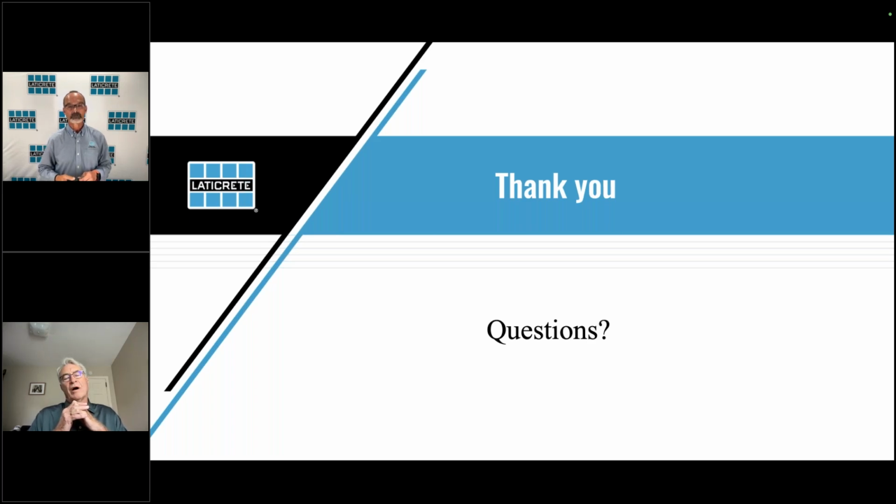So like every webinar, I talk about how important manufacturers' recommendations are. They supersede TCNA or anything that we have. And if this question came up and someone called, would you have a technical rep or someone that could go look at the compact gravel and help make a decision? No, not really. I wouldn't expect that. Yeah. Okay. We just don't know the history of it, right? I mean, gravel is one of those things. I could compact it over something loose and it could appear to be great, and then by January, the substrate below the 1/4 minus is now saturated and it's just jello. So I think that's a field call.